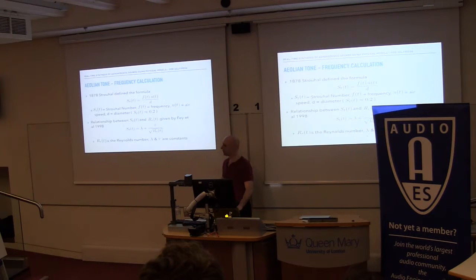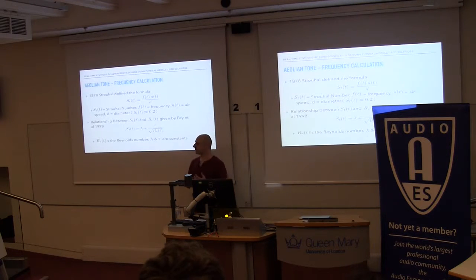And this is where I start looking at formulas. What do I need to know? I need to know the frequencies that are generated. So a lot of the time I'm looking back in history, because to solve these without solving Navier-Stokes, and to do it in real time, you can't really look at computational fluid dynamics. You're going to look further back, to the 60s and 70s, when they did tons of work, before all this processing power was available to solve Navier-Stokes, on finding semi-empirical equations that will predict the sound that's produced.